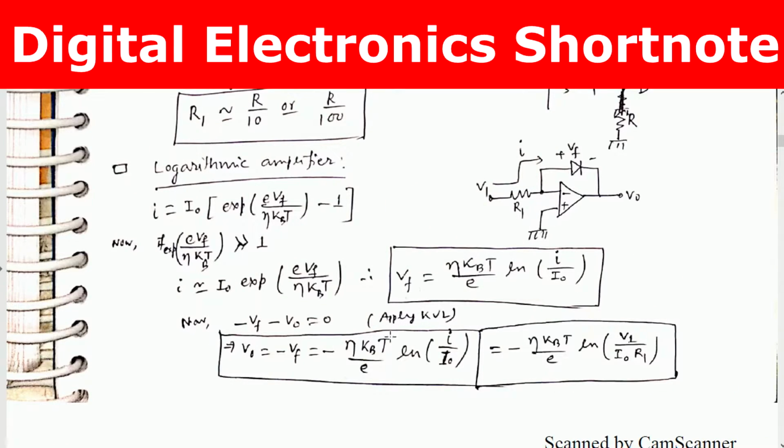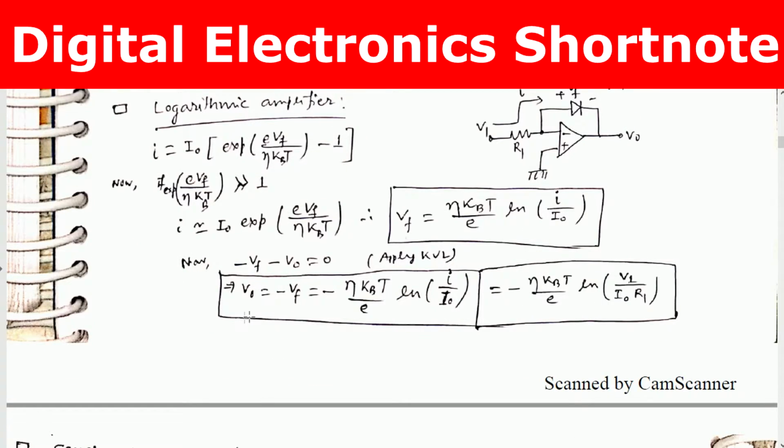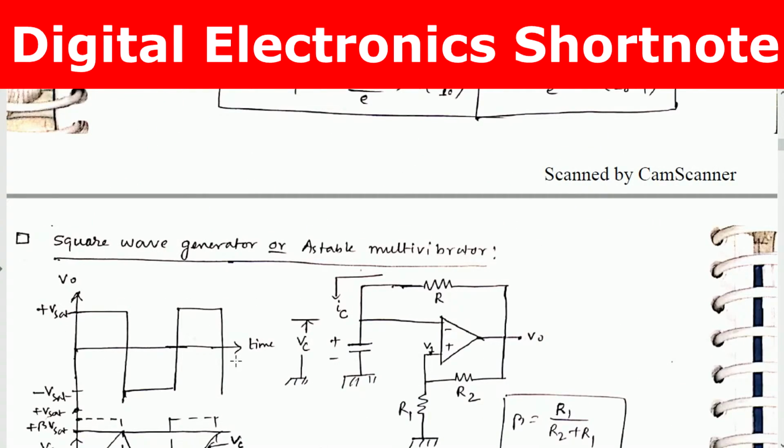Now applying KVL in this loop, we get minus Vf minus V0 equals 0. Therefore V0 equals minus Vf equals minus eta kT by e ln I by I0, that is equal to minus eta kT by e ln V1 by I0 into R1.